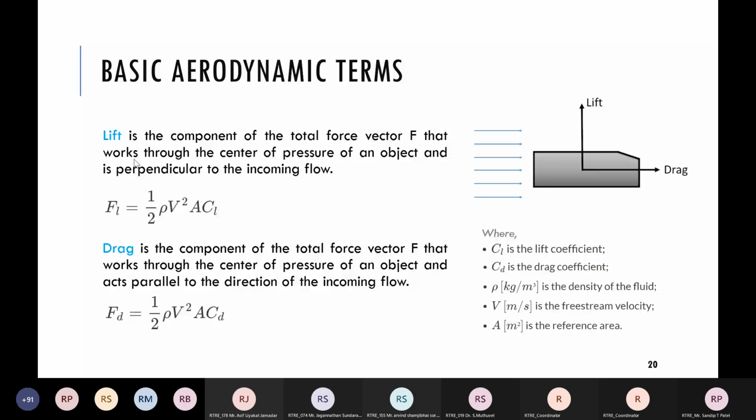A more streamlined object has more lift, while a bluff body does not have that great lift, but has great drag. Every body, streamlined or bluff, has some amount of drag and some amount of lift. But in a streamlined body, in a particular orientation, drag is very low, negligible compared to lift, while in a bluff body, drag is very high compared to lift. That's why we sometimes don't bother to show both lift and drag for a particular case.